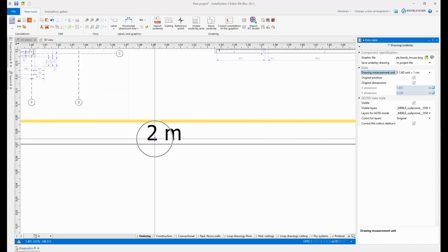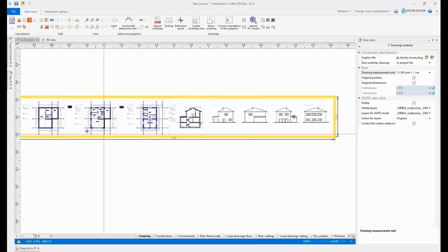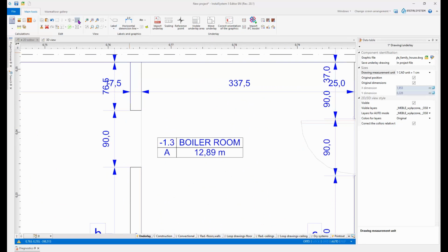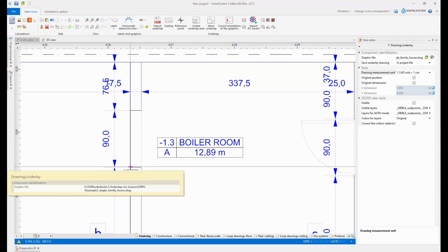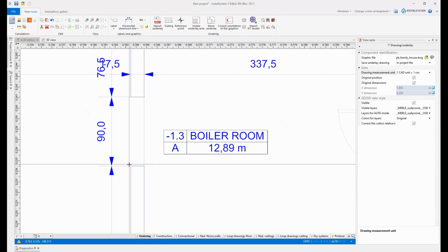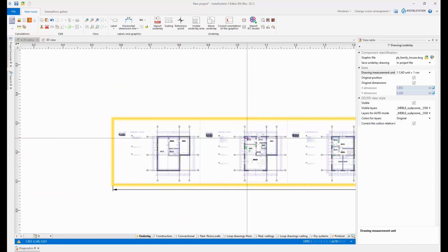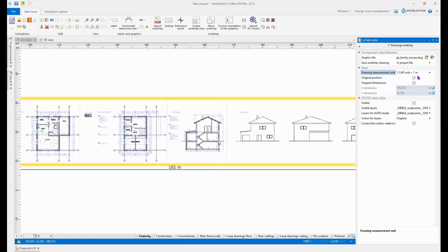First of all, as you can see, the width of this drawing is only 2 meters. And also, if I check the same size, program will show me that this is, well, 1 centimeter. So that's the information that the scale is incorrect. You should choose another unit and check it once again. For our drawing, the proper unit is 1 meter, and we can leave it.